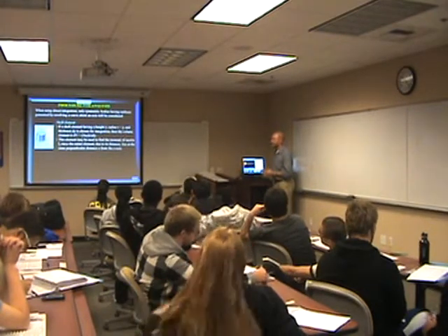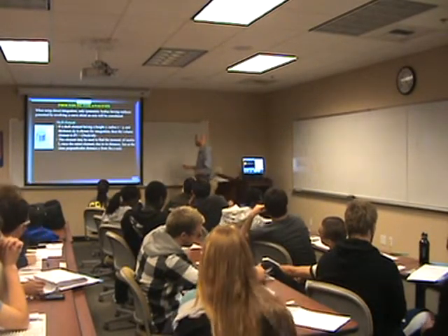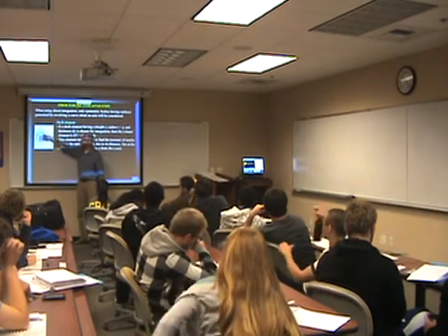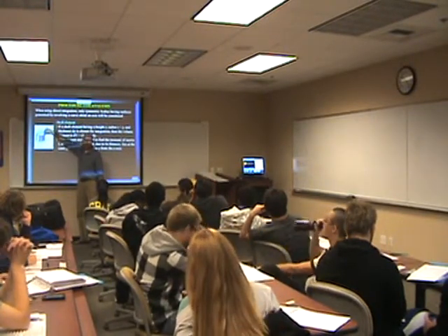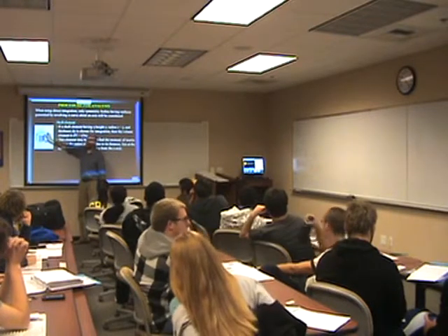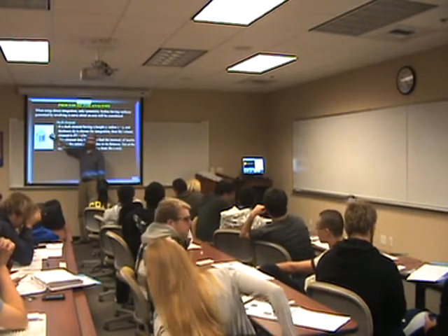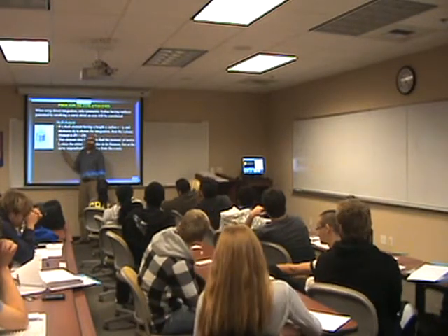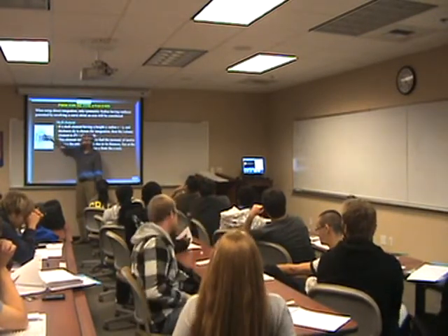So direct integration. We have a shell element, so this is our surface we're trying to do the integral of. This is our shell integral, so we basically have a little dx, and then we have a height. So it's mass times radius squared is the integral. So what is I for this?